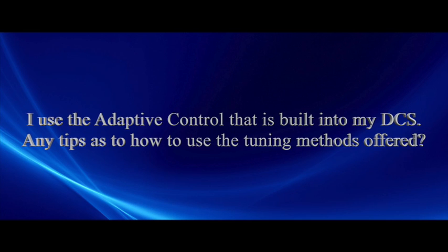thinking of dead time. So if the dead time is 10 seconds, I would think, well, the fastest lambda I really ever want to consider is 10 seconds, but if I wanted to handle nonlinearities, I would go with maybe 20 or 30 seconds. Going 2 to 3 dead times provides more robustness and less oscillation.